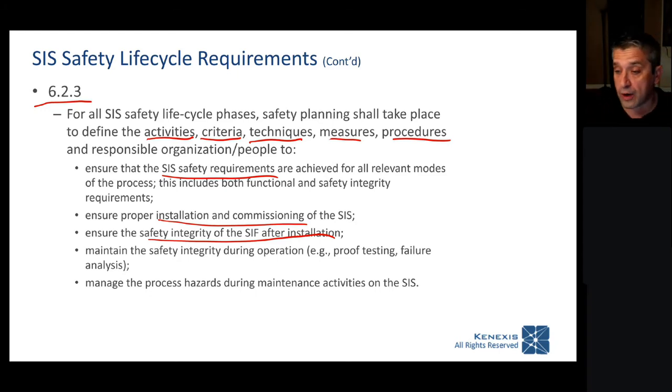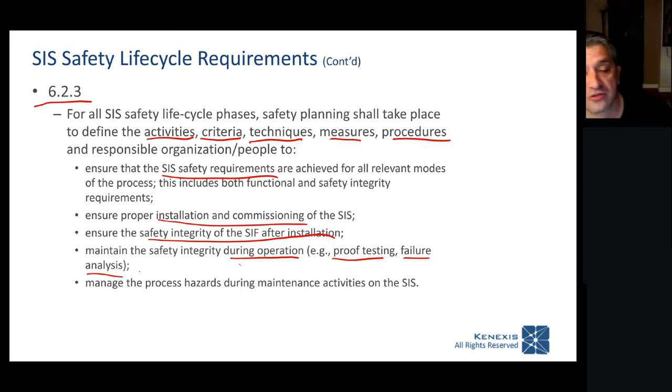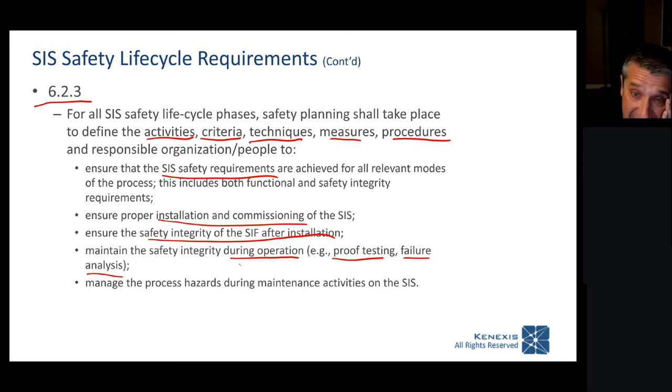So we're going to write requirements not just for the design phase, but also for the operational phase. Maintain the integrity during operation. So we necessarily need to assign tasks related to proof testing and failure analysis. And we also need to manage the process hazards during maintenance activities.